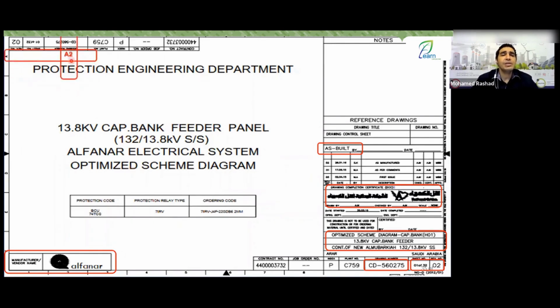Then comes something very critical that we always use when reading our drawing. This drawing has something we call the zone. What does zone mean? As you can see here, you have a set of rows with letters and a set of columns with numbers 1, 2, 3, 4, 5, and so on. So when you're inside the drawing, it comes to tell you that this contact is specific to the axle located in the place called A2. Do you understand where A2 is? Because it will tell you on page 30, A2. So of course, when you're on page 30, you'll find many things drawn. Which one of them is A2?